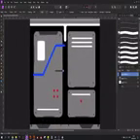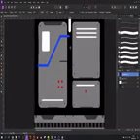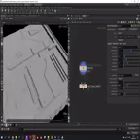And with this workflow we can easily go back and forth between drawings and our generator. So if I make a change in my drawing, I'm going to add some more detail. Let's say I want another line that goes like this. Then I save it. Then back in Houdini I'm going to press the reload button. And you can see that the detail has been added that we wanted. So it's a nice system to work with and it's easy to go back and forth between a simple drawing and your geometry.